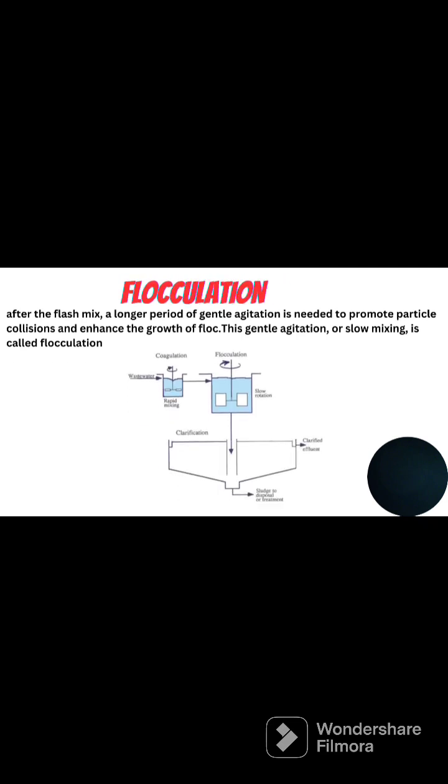Then the next process will be flocculation. In flocculation, sometimes flash mixers are used, followed by a long period of gentle agitation, which is needed to promote the particles to settle. This gentle agitation is known as flocculation.